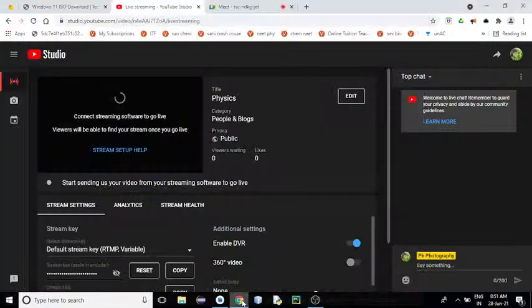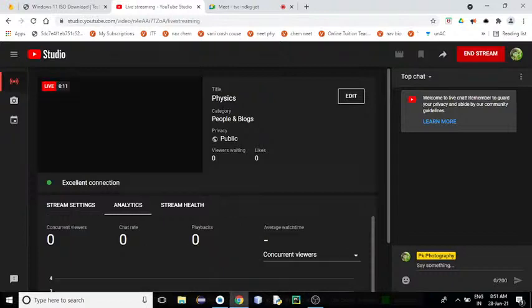fiber. So then you have to write the neat block diagram and explain how the analog electrical signal will be converted to your binary electrical signal, and after that you're going to feed it to an optical transmitter. There, in an optical transmitter we are using a light source. It might be an LED or a laser, through which you're passing the signal to the optical fiber. So that is your transmitting section.